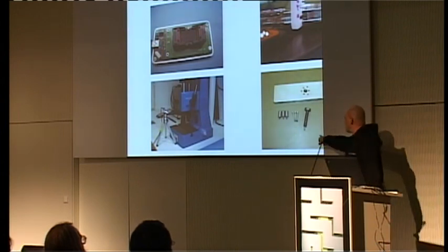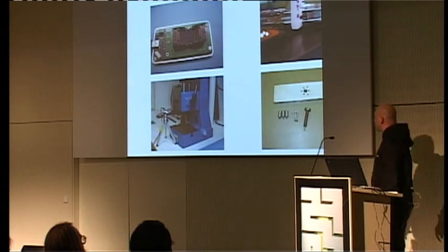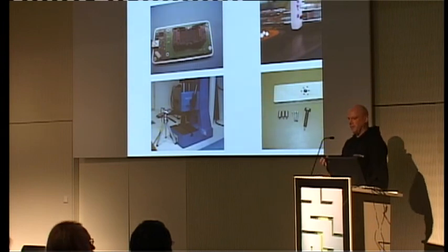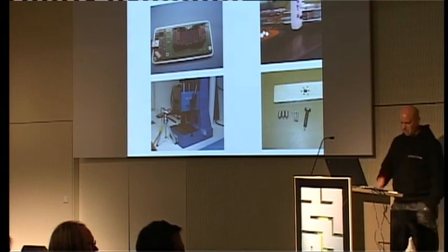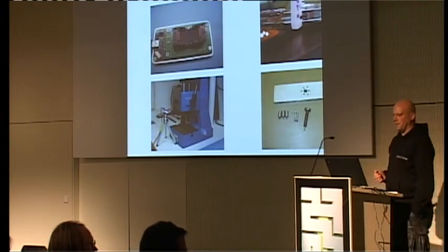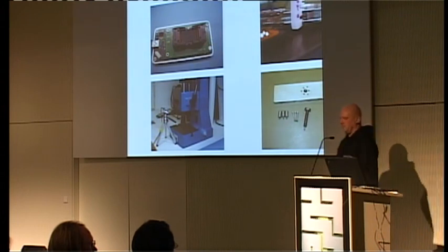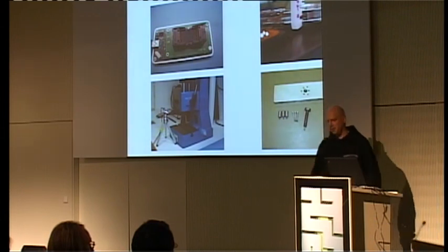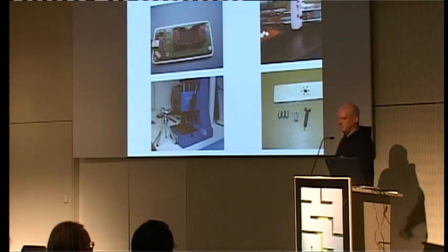Here, this picture looks a little bit like a bar. That's actually to extract the platter hub from the spindle bearing. That is necessary once the bearing gets stuck and you cannot disassemble the platter stack due to accuracy constraints, then you have to take off the whole platter stack at once. And that is one tool for one specific hard drive to do that.